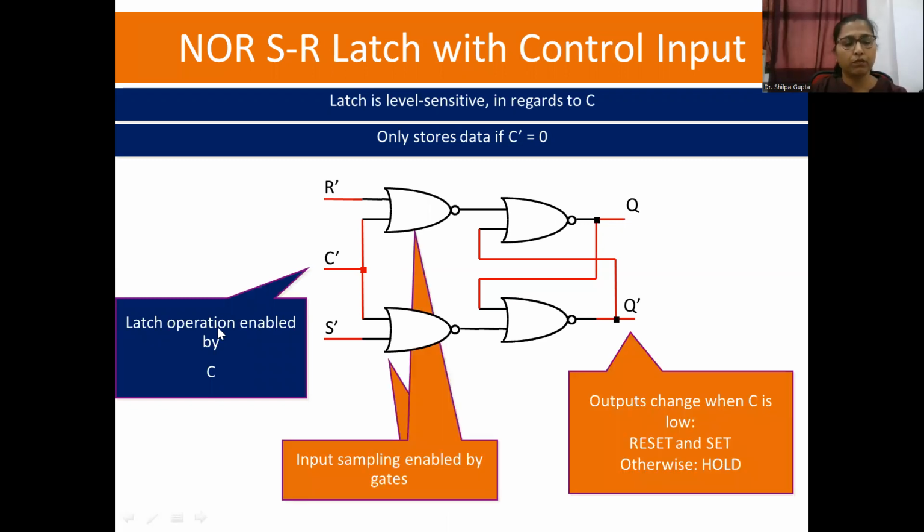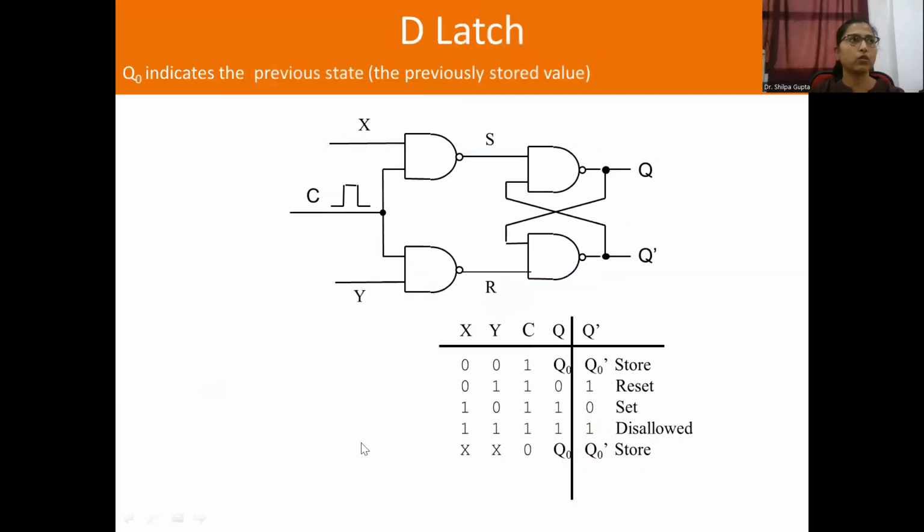Here I've put some bookmark slide marks here. The latch will operate whenever this C signal is set at 0, because you can see here a dash representing the active low signal. If 0 is there on the signal, that means it is active. If it is 1 on this input signal, then it is inactive. Okay, rest all things are same as was in NOR gate.